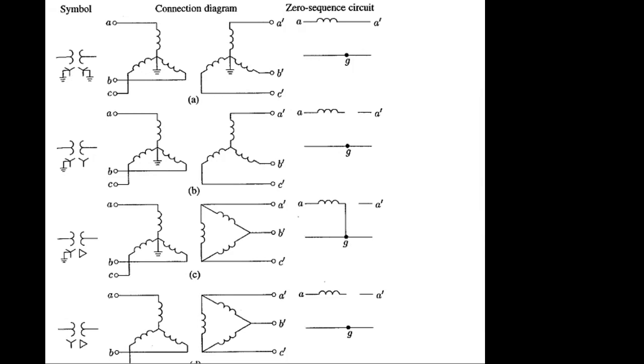Now let's move back to our original scenario. Remember that they are different. This is the zero sequence circuit for YY grounded. And here you can see if it is not grounded, you have some open path, right? Which part is open? In primary or secondary? This opening connection or open path? Primary. It is in primary, sir.